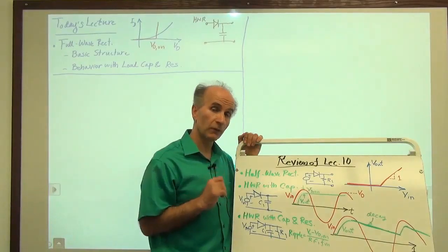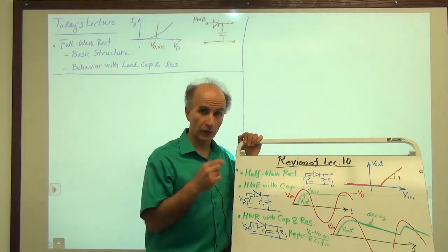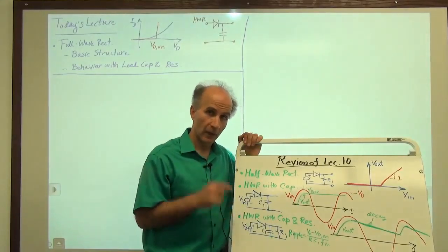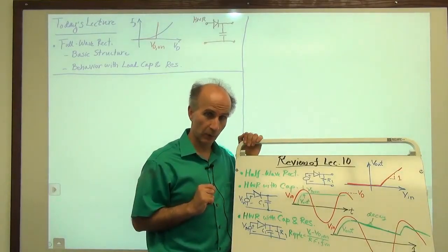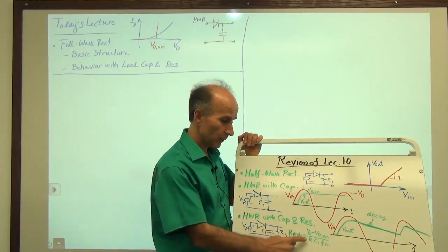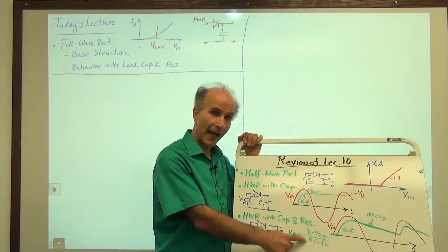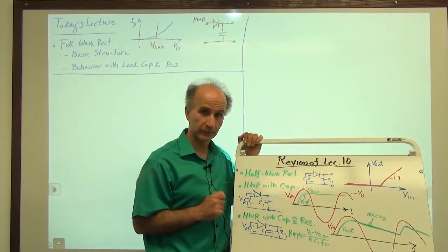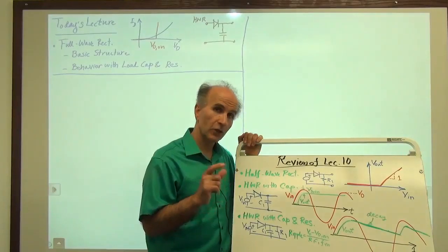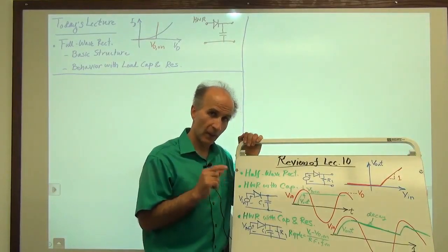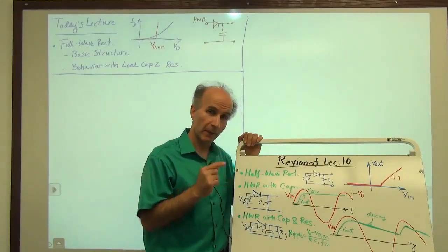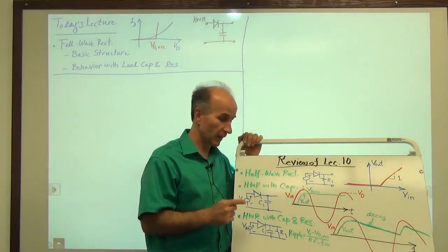Now we're going to go to the full wave rectifier. And I should tell you right off the bat why a full wave rectifier is better. There are 2 improvements when we go to the full wave rectifier. Number 1, the amount of ripple that we get is approximately half of what we have here. So that's one improvement. The other one is that the maximum reverse voltage that is needed in a full wave rectifier is about half of what is needed in a